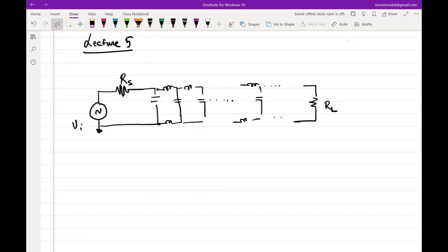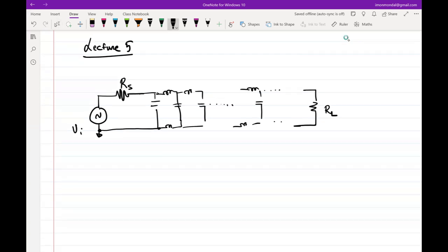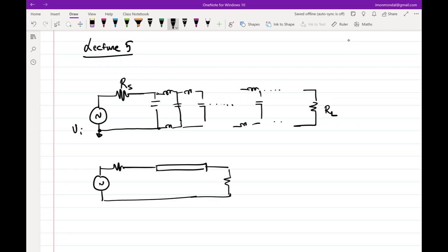I am putting up this type of modeling because there is something about the transmission line which is quite simple, but it is not evident if you do not represent the transmission line like this. The part that I'm referring to is this. If I simply draw the line as a line and I do not show any return path, it might appear to you that whatever current is flowing in here is the current coming out here. But that's actually not the case for all time t, because there are paths from which the current can escape. So that is something you should keep in mind. Again, very obvious, but not explicitly written in books.